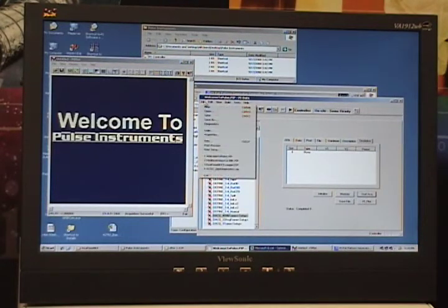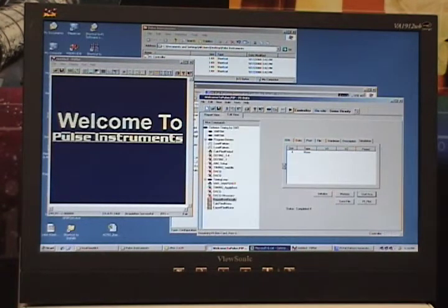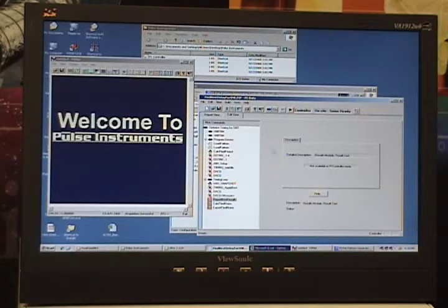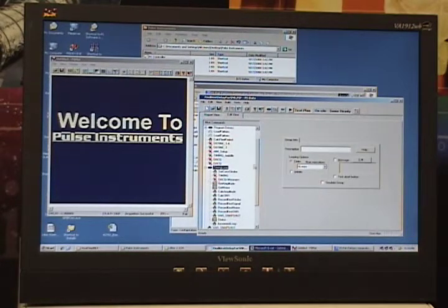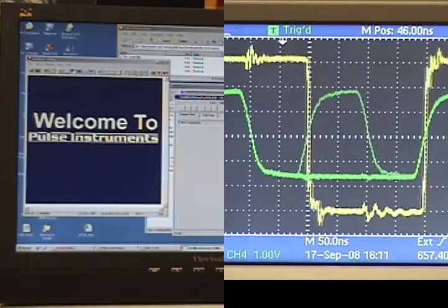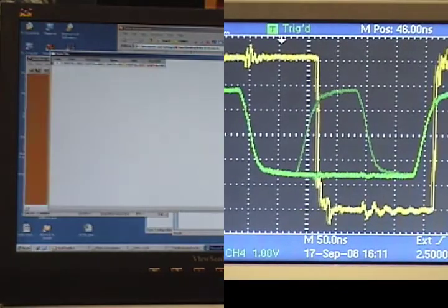Now let's move on to a demonstration of our automation features. Previously, we showed how the placement of the conversion strobe can be controlled manually. This time, I'm going to run an automated test plan. This test plan sets up 100 loops. On each loop, it will step the convert strobe position by 1% of the pixel period, collect 32 frames of data, calculate signal amplitude, calculate pixel noise, and report signal-to-noise ratio.